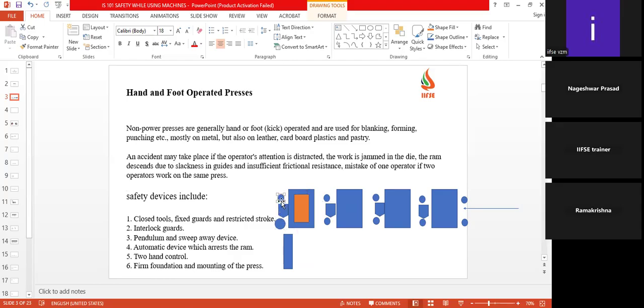Maybe this person sometimes interacts, or while placing the part, the operator who has control may not see the opposite person. So we thought of putting a control here also. Both persons at the machine have to press two push buttons, not even a single push button, as again that would be a gap.